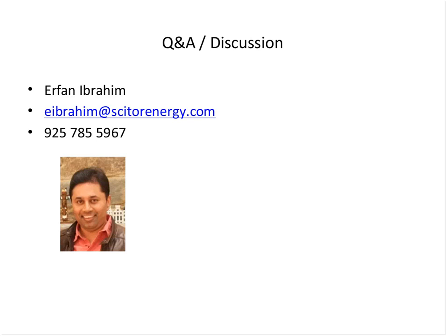Yes, and there are data diodes available, and as I mentioned, the company SecLab Solution is providing that now, and this is very important for the nuclear industry, where there are different levels of security based on whether you're in the radiation portion of the nuclear reactor or the non-radiation portion. There are 4 levels of security in the nuclear power plant. And you need something like a data diode so that you can't do exfiltration of data. Only acknowledgements go back that are authorized. And that's why it's called a data diode. So data can come in from outside sources, of course with the filter, but only specific acknowledgements will go out and nothing else. And only devices at the hardware level can actually do that effectively.